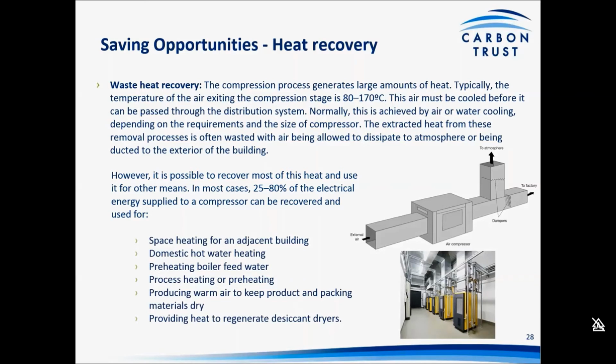Just on that, you see that the diagram has the external air being ducted into the compressor. Best practice is to duct the air from external so that it's as cool as it can be. The cooler the air that you introduce into the compressor, the higher the efficiency of the compression process. It would be very common just to see a compressor in the compressor house hauling in the warm air that the machine is exhausting, as opposed to having the warm air taken out of that space and the cold air brought in from external. So it's just one to remember.